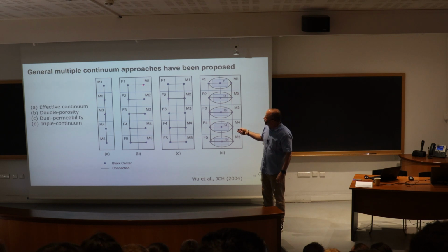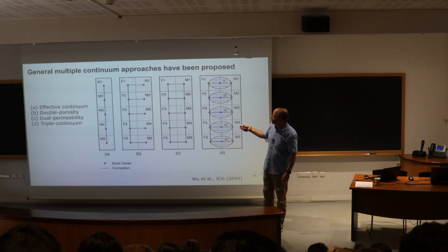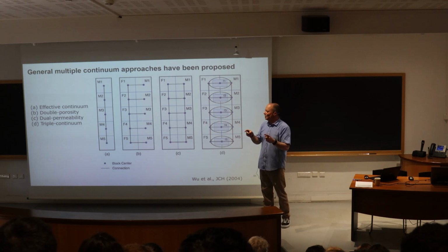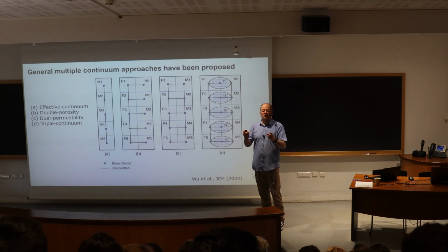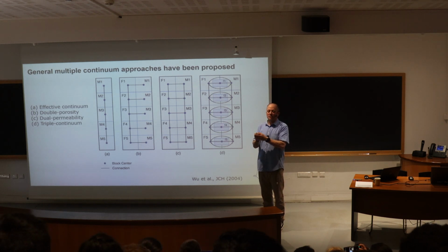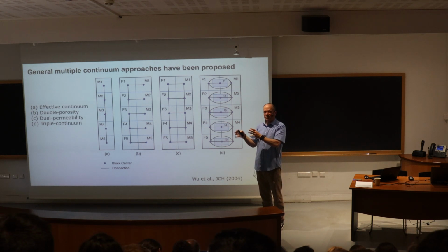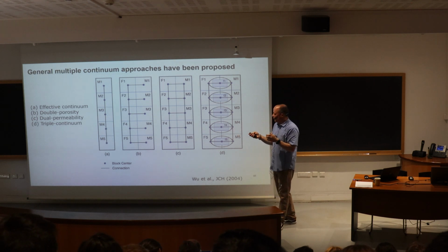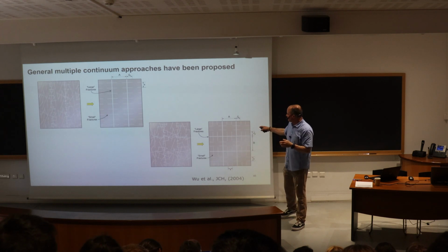The double porosity approach here shows that there are two systems now, the fracture system and the matrix system. So in your model you would have two unknowns for every cell. You would have hydraulic connectivity of the fracture system, hydraulic connectivity of the matrix system. You would have to define properties of your fracture system, but fractures without considering the matrix, and properties of the matrix system.